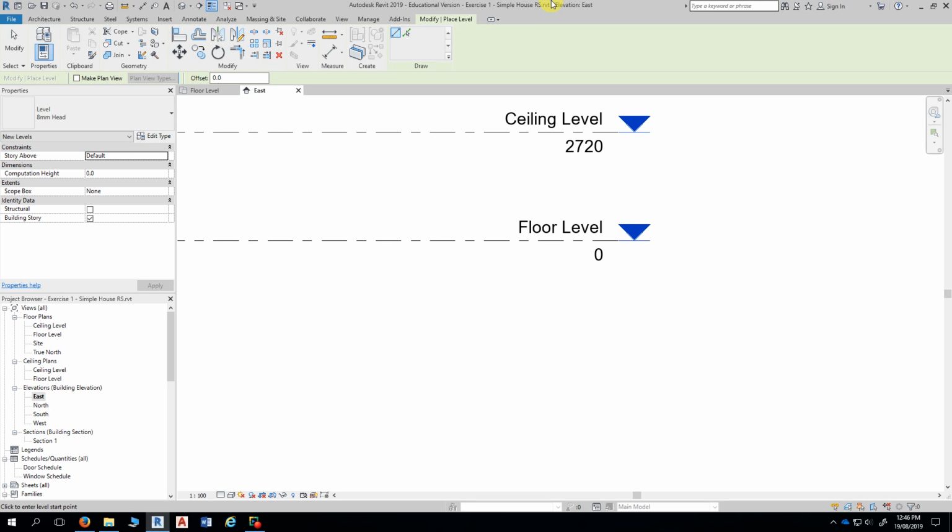So we didn't go and delete those other views after when we created this floor? Yeah, because we went through that in a previous session. By default, when you create a level, it'll automatically create a floor plan, a ceiling plan, and a structural plan. But if we untick this option here, it's not going to create any plans at all. Okay, so to produce a non-story level, we untick this option here.